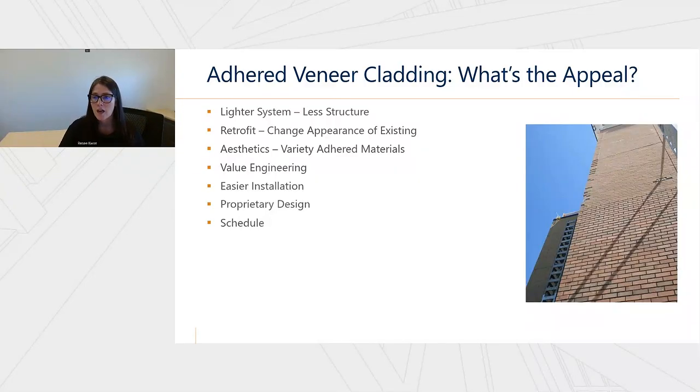We say that perception because we're going to go through some of the challenges with installation, but there's this perception that maybe you need less skilled workers to install these systems. There's proprietary designs out there, so you basically select one manufacturer that can provide the entire exterior wall system. And then schedule, decreasing the time for schedule may be another factor influencing this.